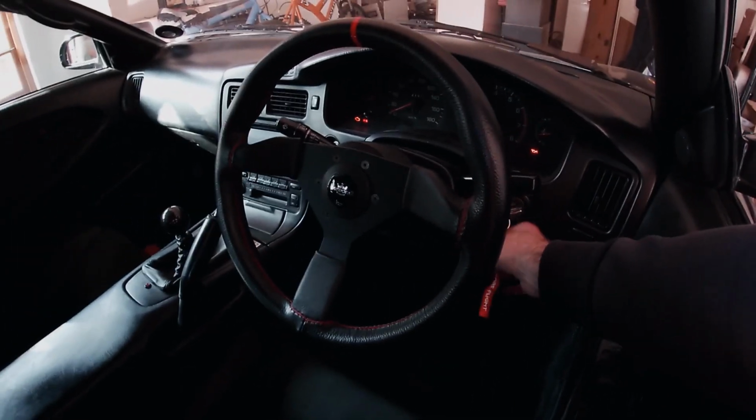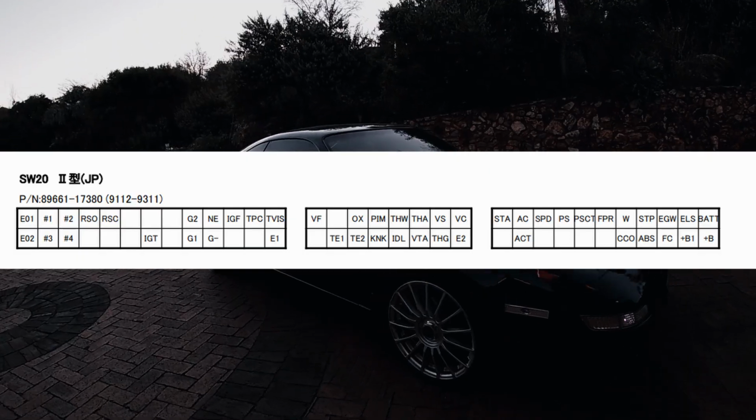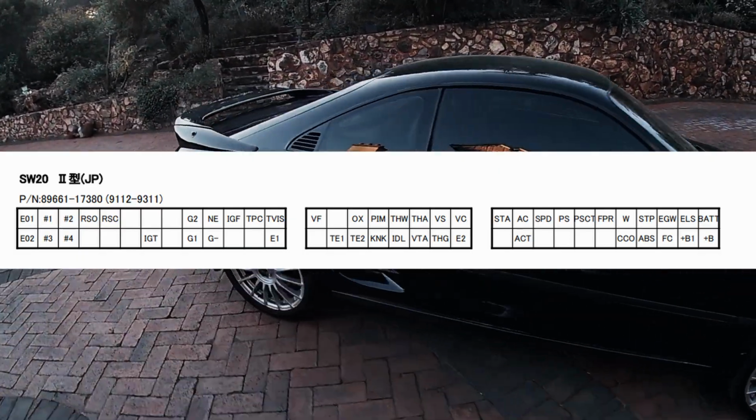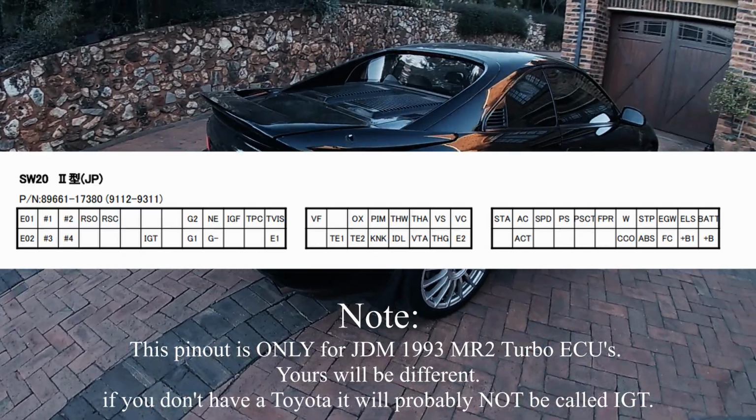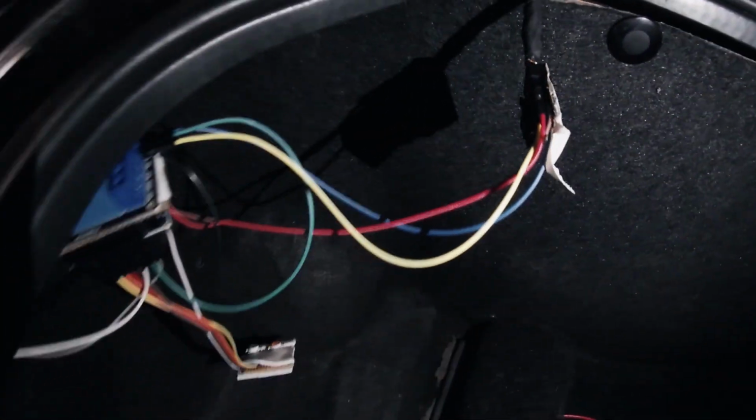I actually got the idea to do this after removing a piggyback ECU called a Unichip, which was causing some fueling and timing issues on my car. When I deleted it, I found that it was tapping into the IGT, TPS and AFM signals on the ECU, which was lucky for me since the harness they added gave me an easy way to tap into the wires, which I pretty much wouldn't have done otherwise.